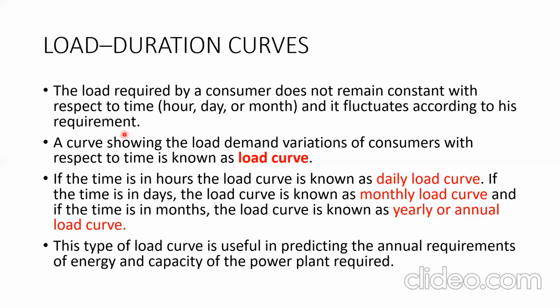Such cases are there, for example in malls, offices, institutes. Everywhere the loads are switching on and off as per the requirement. So the load fluctuates according to the requirement of the consumer. A curve showing the load demand variations of consumers with respect to time is nothing but a load curve. Variation of load with respect to time.